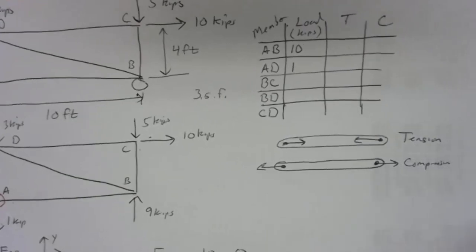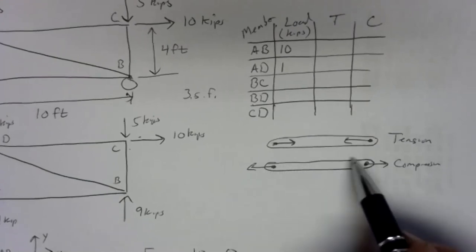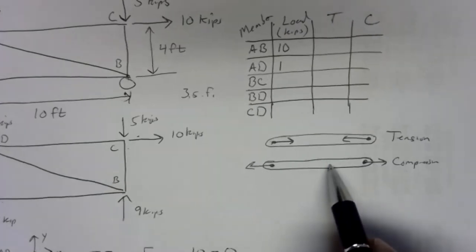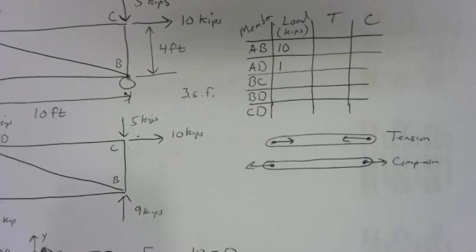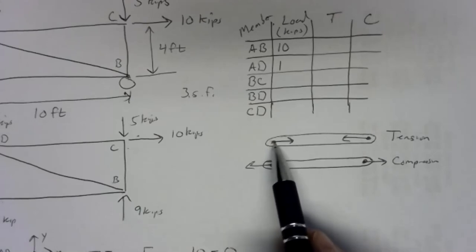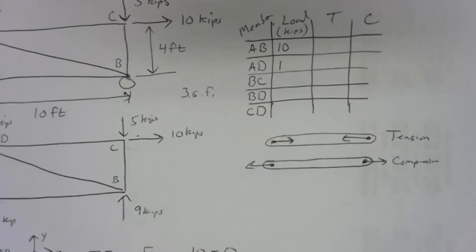and compression. Now, if you just looked at that without having the context of going through the discussion, you might think that looks totally and completely backward. But remember, what we're looking at here is kind of a shaded out ghost image of the member. We're really looking at the joints. And a member in compression has been squeezed. It's trying to expand back out to its original size. And so it's going to push against its supports. And it's going to push them outward. A member in tension, think about these as pegs in the wall. If you take 2 pegs and drive them into a wall, take a big rubber band and stretch it out and hang that on those pegs.